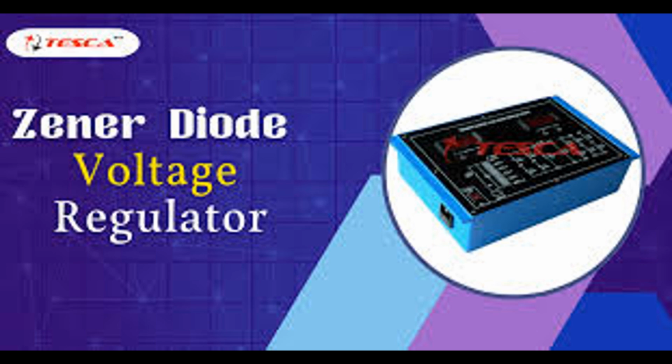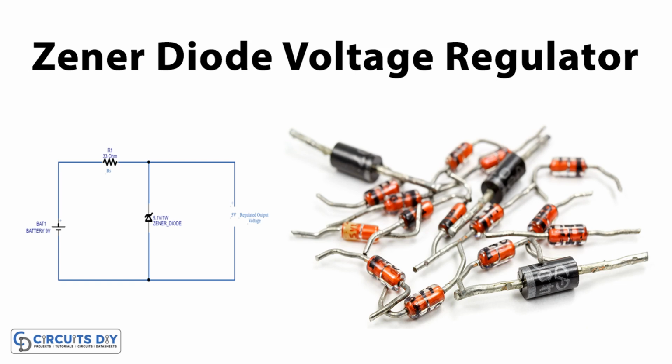5. Temperature coefficient. Effective temperature. The Zener voltage changes with temperature. This change is expressed as the temperature coefficient, usually in ppm/degree C or mV/degree C. Positive/negative coefficient. Zener diodes with a Zener voltage below 5.6 V typically have a negative temperature coefficient, while those above 5.6 V have a positive temperature coefficient. Diodes around 5.6 V can have a near zero temperature coefficient.